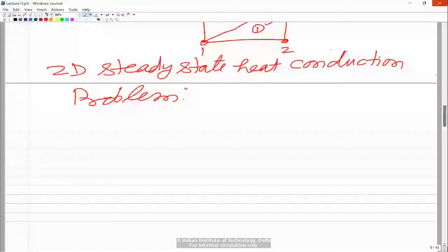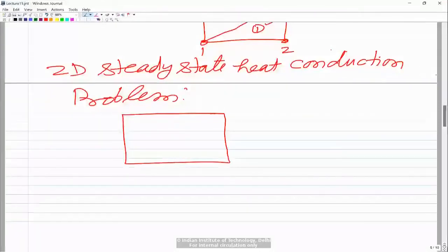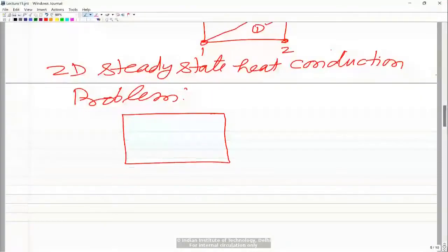Now let me say that we have a rectangular domain over which we want to study the heat transfer. Say in an engine room, you have to dissipate the heat from the engine, and there are fins which can be treated as rectangles, and we want to model only one particular fin. Of course, in 1D we model that as a rod, but you could actually have this kind of plate structure as the heat dissipating device.